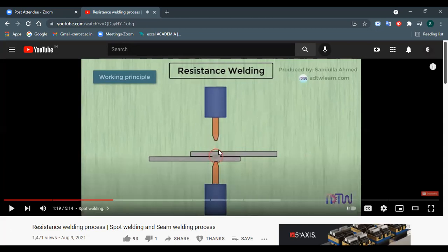You see that pressure is also important, right? Once they are brought to that plastic state, wherein they are softened, you have to apply some pressure so that they get joined at that particular location. They're fused. So that application of pressure is also important. The electrodes are not only there to supply the current and create the resistance. They're also responsible for creating that pressure. Once reaching the plastic, softened state, these electrodes will push them so that they join.